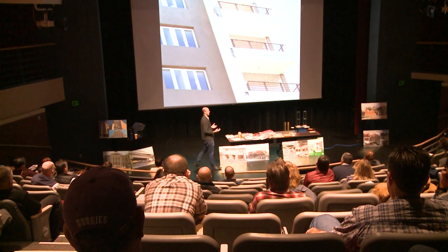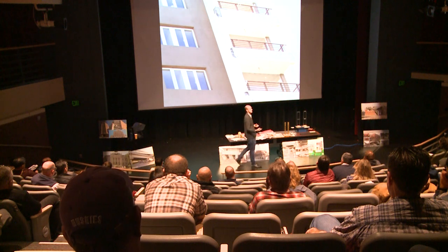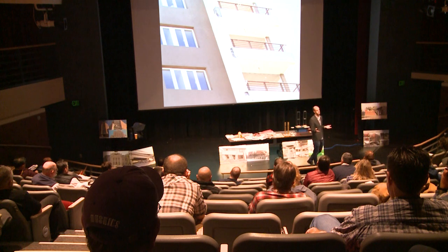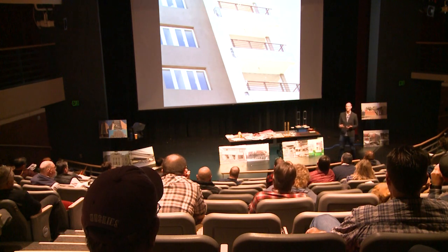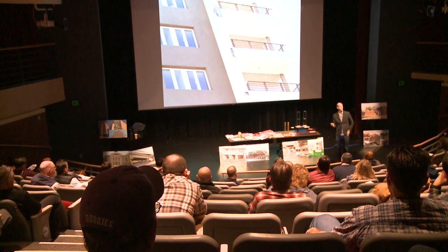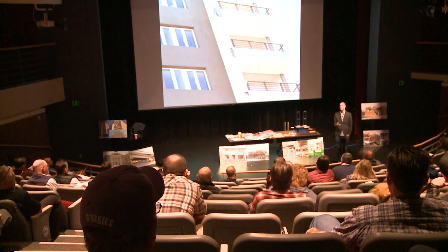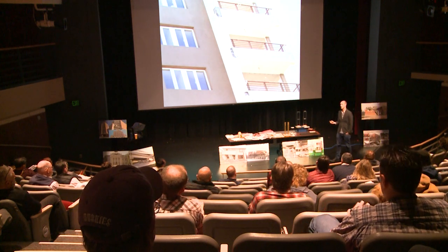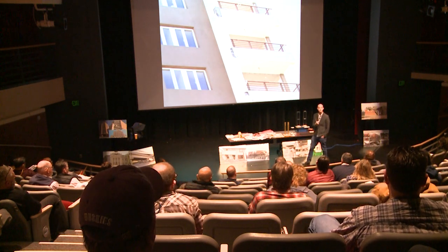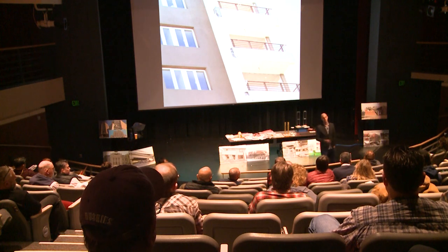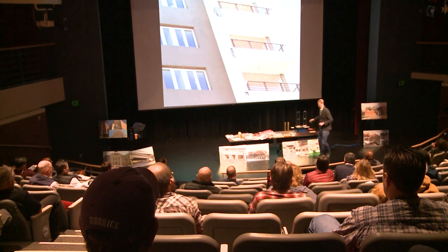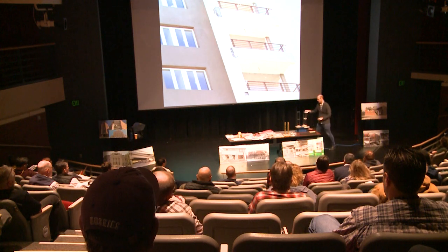In general, are we more concerned about lateral movement from earthquakes or vertical? Probably lateral, because that's the first we've talked about vertical, and we're 6 hours into the day. Why do you suppose our primary focus is lateral accelerations? Well, sorry? Because the force, you get much higher moment down here at the bottom. Yeah, we have our, use my model.